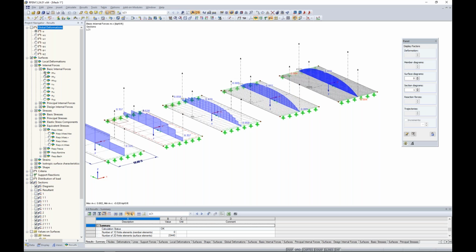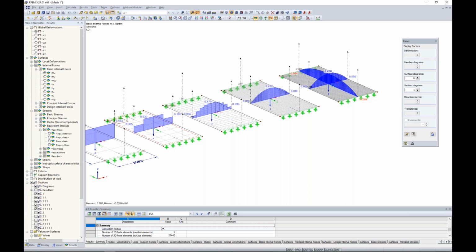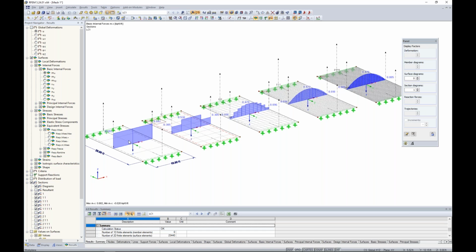Now we can also view the same concept with our MX forces, and I will turn on here my diagrams in the other direction of my section cuts through the surface. Same thing. You can see that this diagram here is definitely not what we'd like to see, but as we begin to move down the line, we're seeing a little bit more realistic behavior here. But again, take a look at the max bending forces, 0.479 kip feet, 0.472, 0.47.